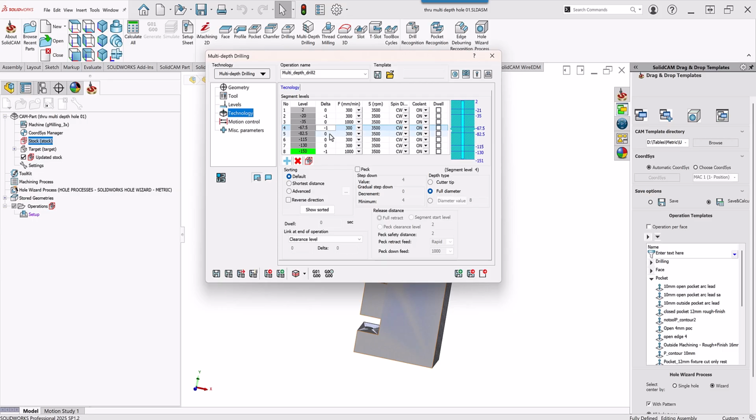And I can do this all the way down. This one, cutter tip, feed rate 1,000. This one, full diameter. And don't forget, for each one of those where I am actually drilling, I can also use the option of peck drill as well. Go back over here, put in peck. Each one of those I can put in peck.